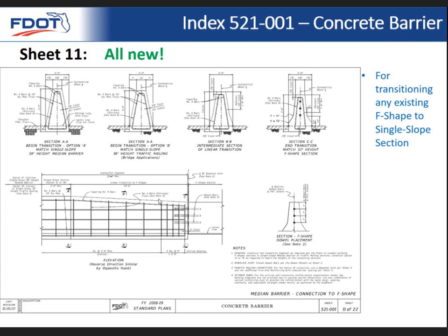And so you have your 10-foot transition, and then before you connect to the new bridge, we want there to be a minimum 2.5 feet. This actually gives a little leeway for the contractor that's outside of this 10-foot, because this will probably be a pre-made mold. And so then they have 2'6" minimum to make that connection to the bridge, because you're basically going to be between two solid objects, and the odds of getting the length exactly right are pretty low. So it just allows some flexibility there. And then also 12'6" is the min, just for dead load considerations.